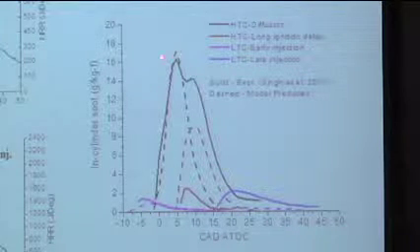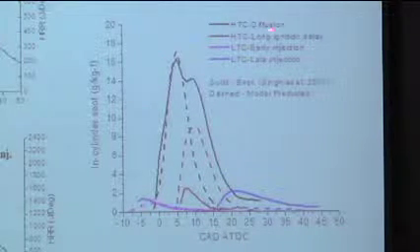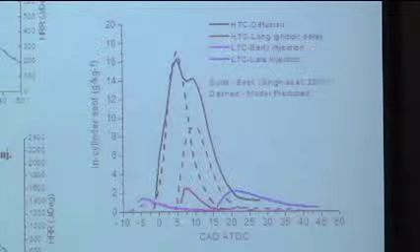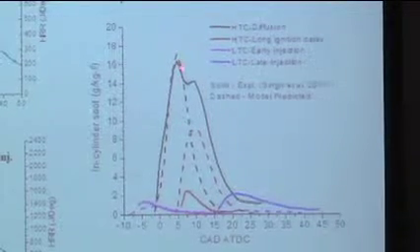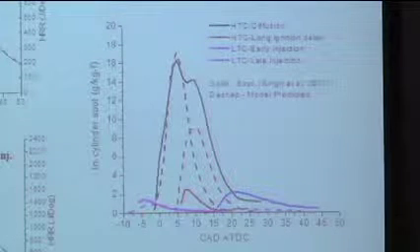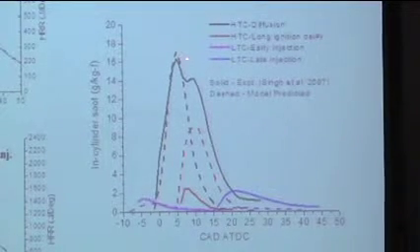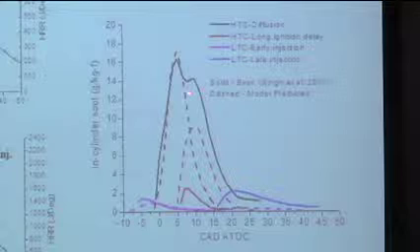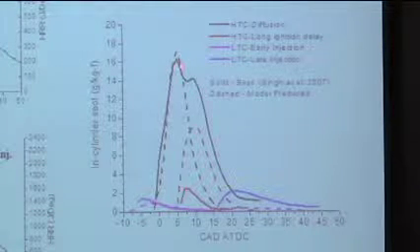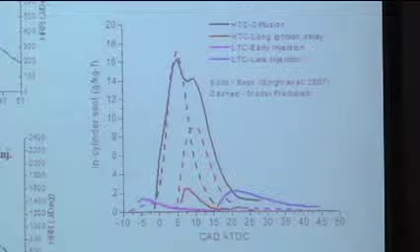So the black data here corresponds to more or less conventional diesel combustion, high temperature combustion with diffusion flame combustion. The experiment shows way more soot than for these low temperature combustion regimes. And the model, the dashed lines here, is able to pick up that trend when you compare, for example, the black against some of these other cases down here.